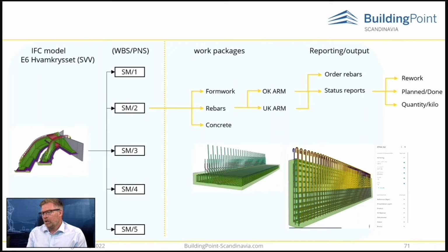So therefore, we are focusing on how you can break it down, so you have all the information regarding formwork, rebars, how much concrete it is, and UK and OK stand for, in Norwegian, overkant and underkant armering. If you have a foundation or a slab, then we're talking about the top bars or the bars beneath. So we divide those into different groups, so it's easier for the worker to understand what type of rebars goes in first, and you can click on it and get the number of it, the distance between the rebars, the bending form and everything.